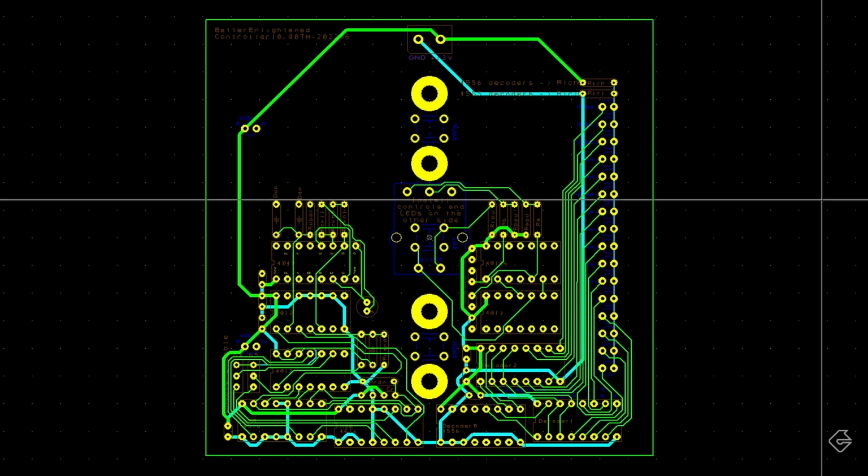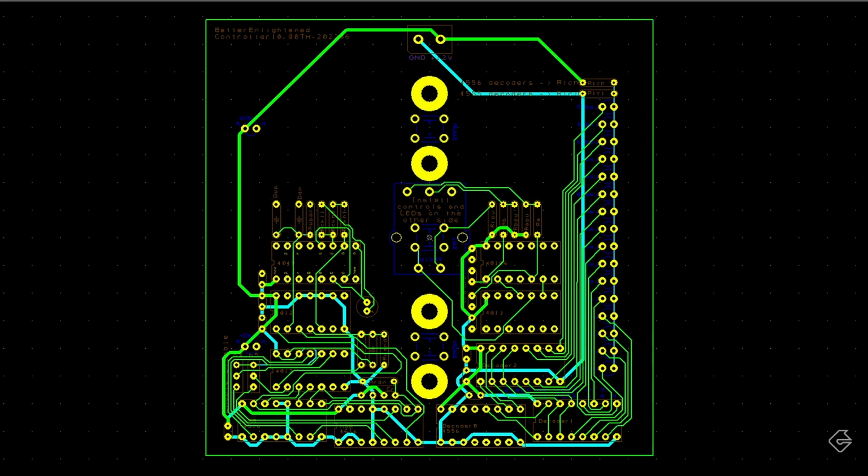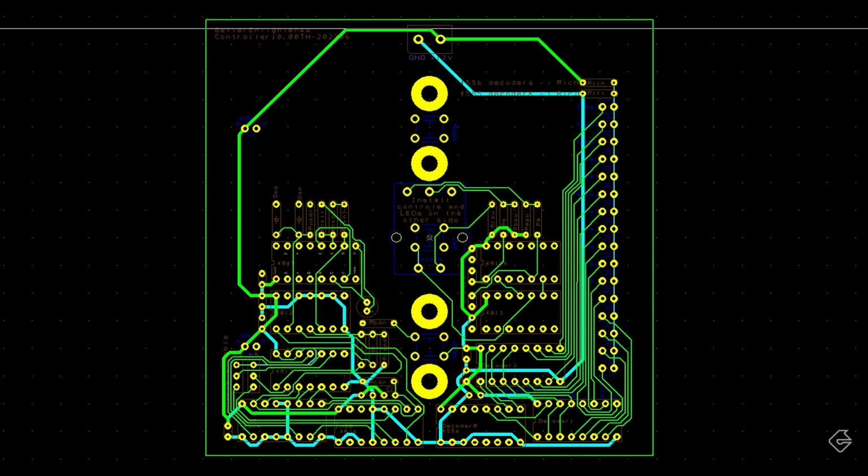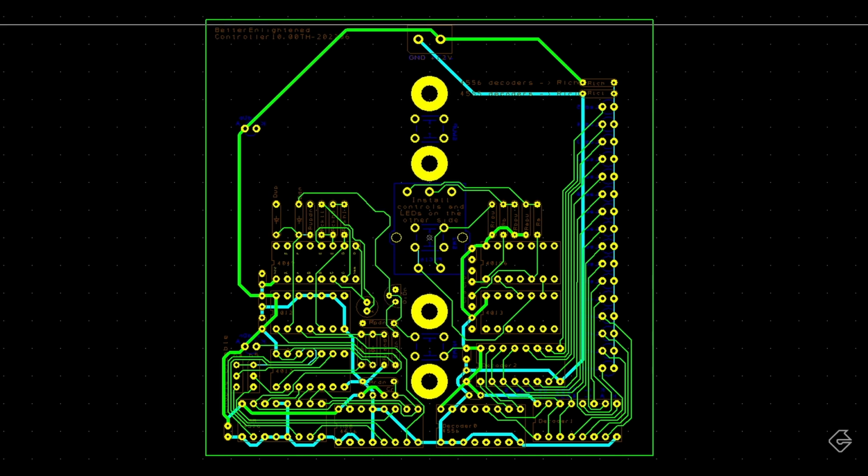These are the non-light emitting kinds. There they are. Next, we'll wire in the resistor for the down switch. Then we'll add in the MOSFET that controls the down LED. Now let's do the MOSFET for the up LED. Now we're going to put the resistor Y and the capacitor Y.